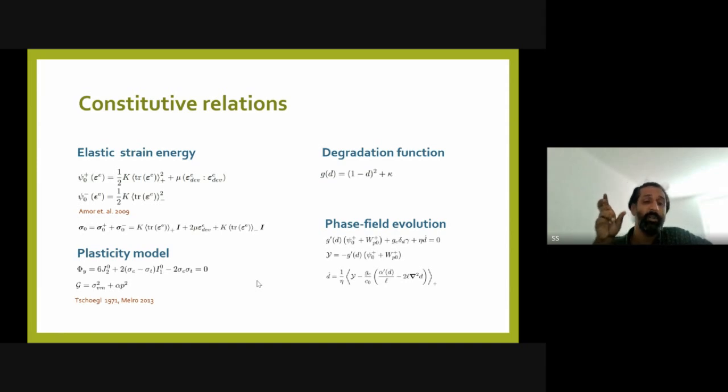The plasticity model utilizes a paraboloidal yield surface criterion, which basically incorporates the effect of pressure causing plasticity in epoxy material. This was given by Sagar in 1971. The plasticity potential function also contains the distortional component from the von Mises stress and also from the pressure. So alpha here is a parameter that controls how much dependence on the pressure there is in this model. But these models have already been developed. We are going to implement this into the phase field equation.